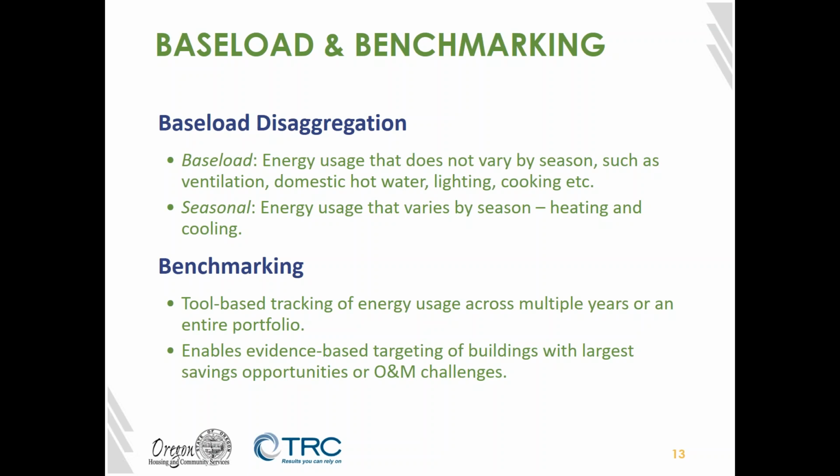So you'll see energy usage that's varying by season, and that's essentially your heating and cooling. To really get a sense of where the opportunities are, particularly if you have a larger portfolio, the best way to do that is to use benchmarking. Benchmarking is a tool-based tracking of energy usage across multiple years or across an entire portfolio. And this enables you to use evidence-based targeting of buildings with the largest savings opportunities or operations and maintenance challenges.